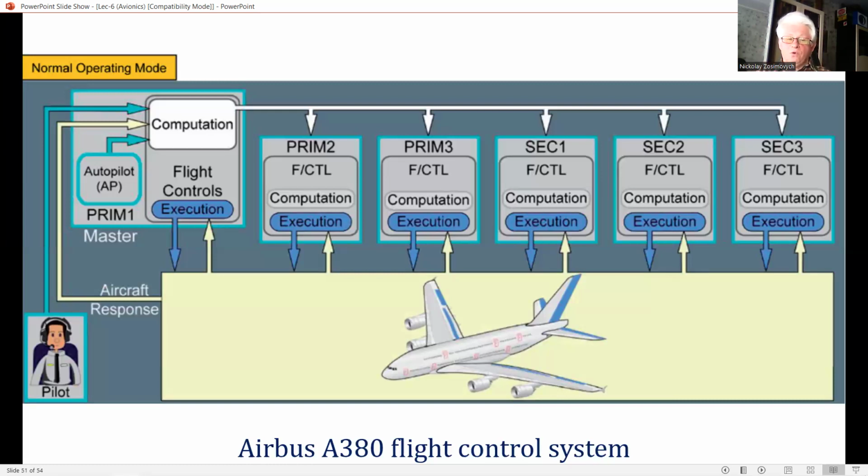Normal flight control law is available after any single failure of sensors, electrical system, hydraulic system, or PRIM. Alternate law, in which auto trim control laws and flight domain warning are available. Direct law: manual trim, direct relationship between side stick deflection and surface position, longitudinal and lateral stabilization, and flight domain warning.